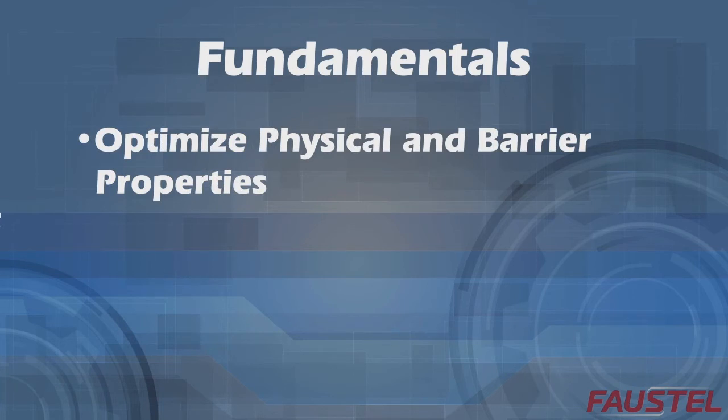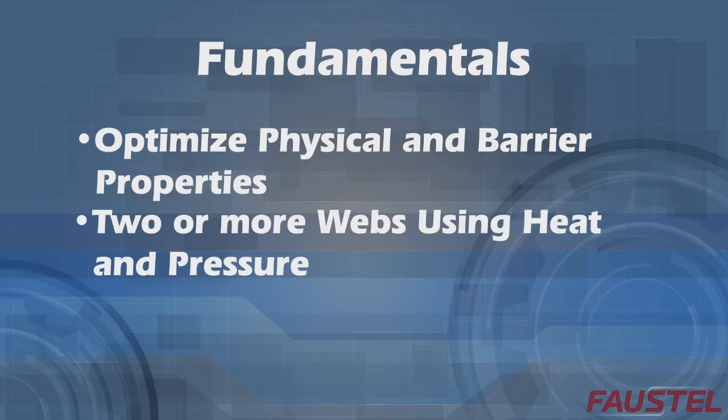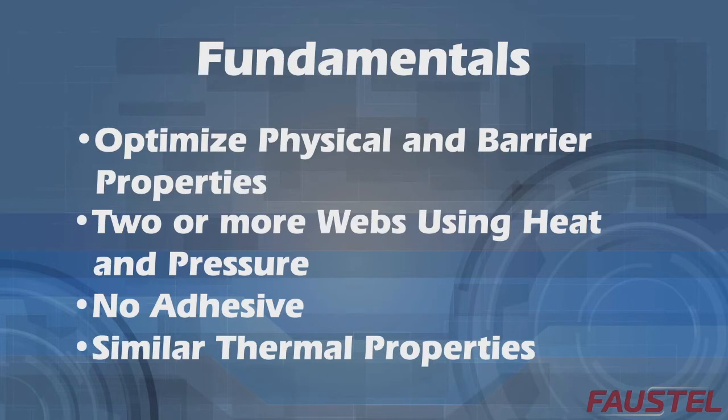Thermal lamination is a process where two or more webs are bonded together using heat and pressure, but without the use of an adhesive. Because the heated materials form the bonding medium, it is important that both materials have similar thermal properties.